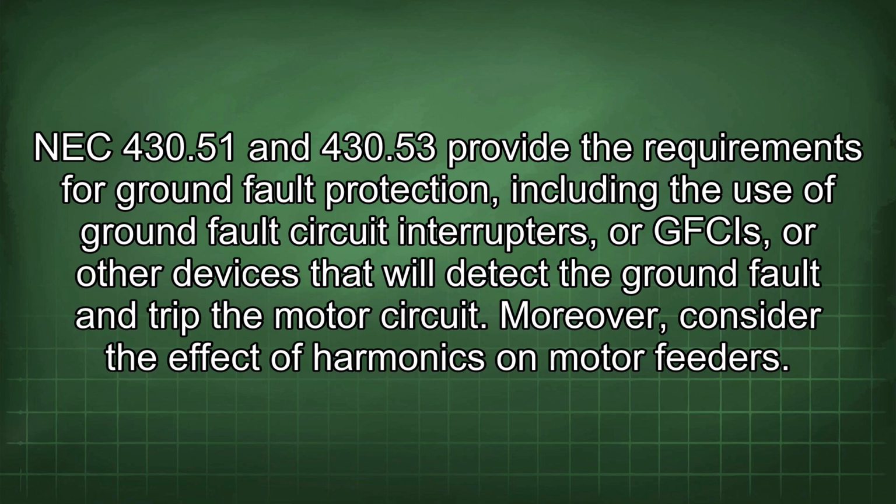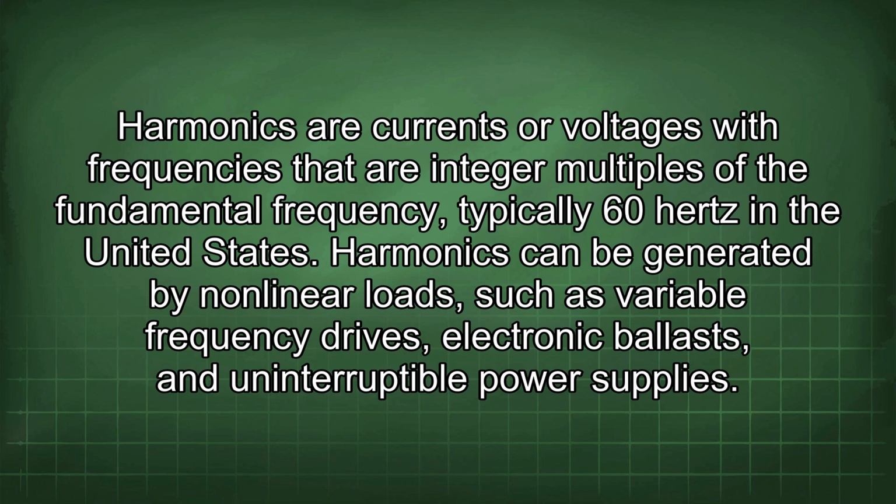Moreover, consider the effect of harmonics on motor feeders. Harmonics are currents or voltages with frequencies that are integer multiples of the fundamental frequency, typically 60 Hz in the United States. Harmonics can be generated by nonlinear loads such as variable frequency drives, electronic ballasts, and uninterruptible power supplies.